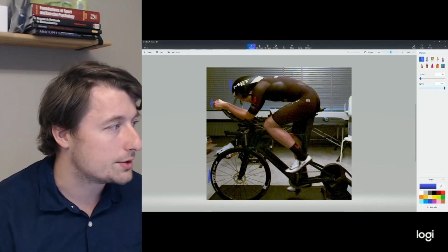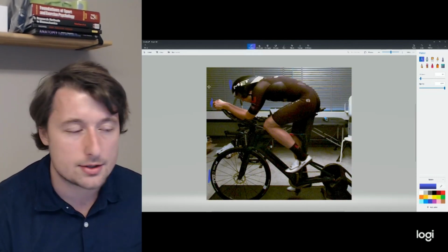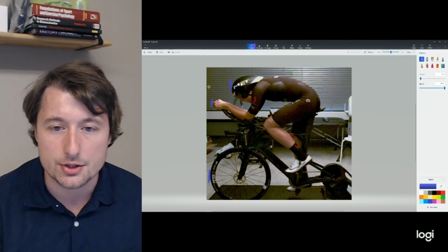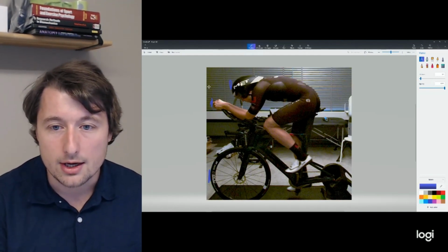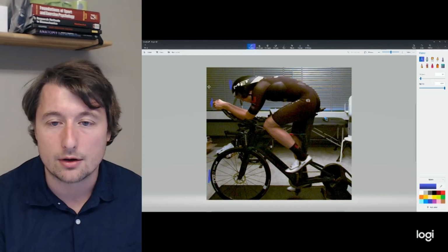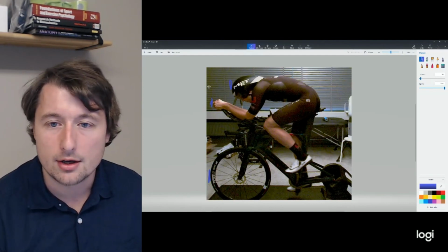So what we're trying to do is to create as much of a laminar flow as possible around the body. So air can move in two different categories essentially. We've got laminar flow and turbulent flow. Laminar flow is going to create a much lower coefficient of drag for us. So that's definitely something we want to try and adhere to on a bike position. So we want to try and keep the air stuck to the body for as long as possible.